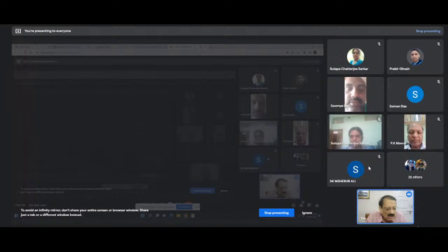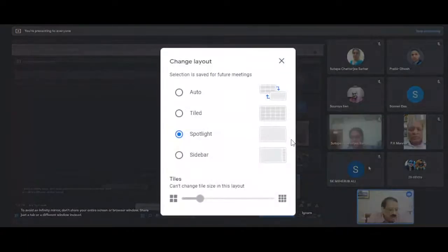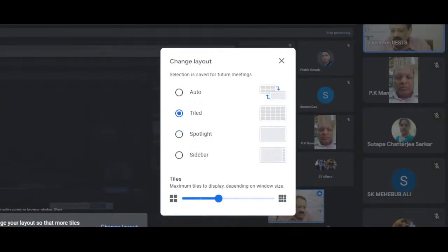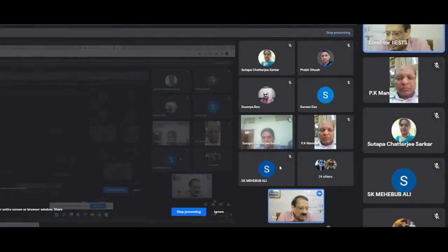So when the material is the same, there is no problem, which you call a homojunction. In a normal p-n junction, if the material is silicon and one side is P, the other side is N, you do not encounter any problem. But all these 3-5 semiconductors which we use are mostly grown in an epitaxial manner, so you need a substrate on which these materials are grown. For example, if you want to grow a gallium arsenide, aluminum gallium arsenide layer, you have to grow it on a gallium arsenide substrate, to which it is lattice matched.